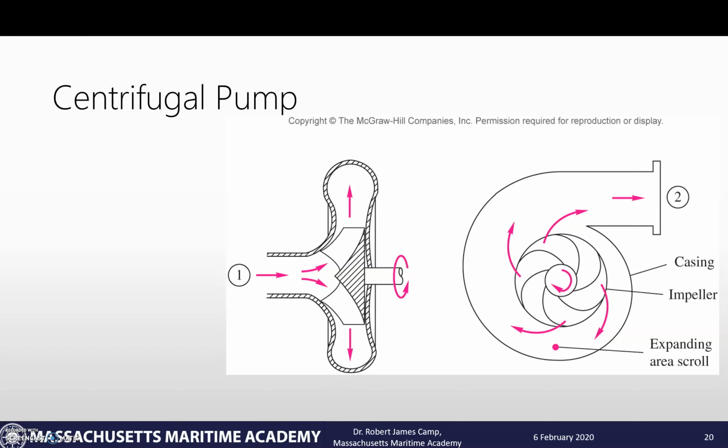So now if we assume a steady flow, the pump basically increases the amount of head that's added from point 1 to point 2. So if we draw a control volume around it, and we neglect any heat work or viscous work in the system, we can calculate out the hydraulic power and then the hydraulic head.